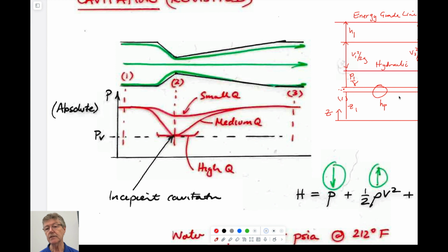The same velocity here as this. So these heights have to be the same. If these heights are the same, then this is Bernoulli without the losses, right? This is Bernoulli's line. And if this is the same and the elevations of these 2 are the same, then by default this is horizontal, and the pressure difference between upstream and downstream has to be the same.